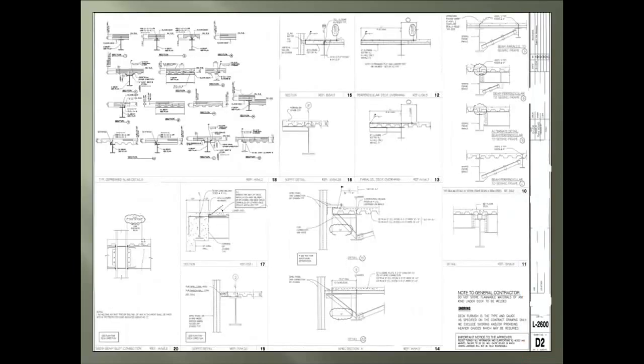Now we move to the second sheet providing information dealing with the metal decking. First X covers different scenarios for depressed deck conditions that are found on this project. Second X covers the SSDA slot moment connections. Third X covers again the bending of reinforcing steel with a different wall condition. Fourth X covers another soffit detail condition. Fifth X covers the window mullions attaching to the deck edge.